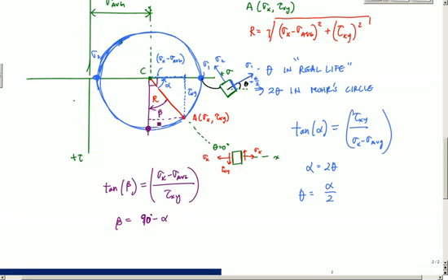Anyway, this right here would tell us, if I want to get to the maximum shear stress state from here, I would start with my original. I had to rotate clockwise an angle of beta on Mohr's circle, which means in real life, to get to this maximum in-plane shear stress state, I got to go here. This is beta over 2. Can you even see that? Let's just draw that over here. This is beta over 2, okay?